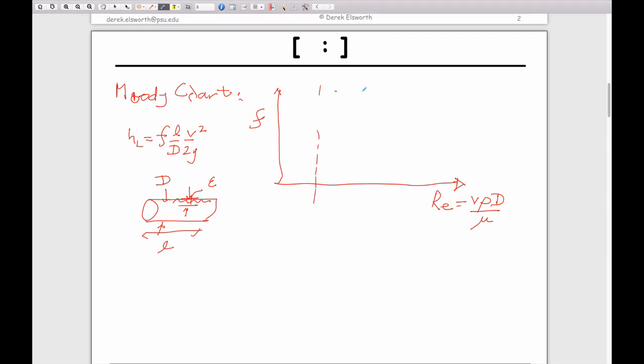We talked about three regimes. We talked about fully turbulent. We talked about laminar. And we made the analogy that laminar means like taking a pack of cards, which are laminae, and scooting them across each other so that the velocities are all parallel to each other, so there's no turbulence in the system. As you increase the flow velocity, all of a sudden you start making eddies, and you move from this behavior at about 2000 to fully developed turbulent flow at 4000.